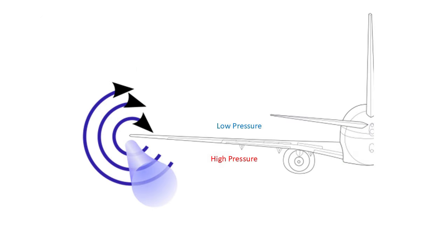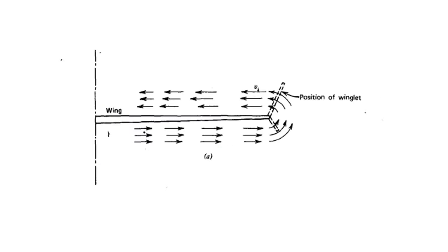At the end of a wing, the airflow is almost circular due to the pressure differential generated in a lifting condition. On the underside of the wing, the flow has a spanwise component moving outboard, and on the upper surface of the wing, the flow has a spanwise component moving inboard. So a portion of the total airflow in the region tends to travel outboard along the span, up and around the wingtip, and inboard once we're on the upper surface.